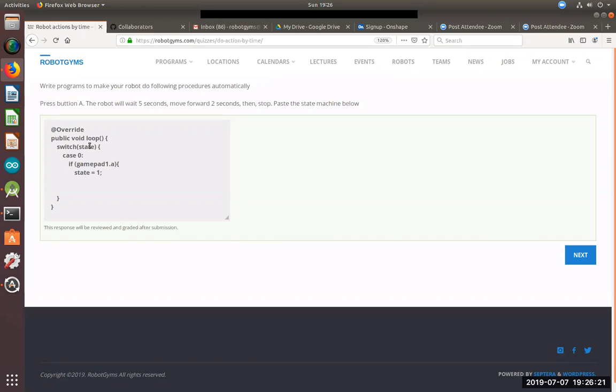And then you have a break. Always remember: if you don't say break, you will fall through. It doesn't check when you come back; you immediately go to case 1, whatever the next case is. You need a break. Most state machine bugs are just forgetting to put a break there. Why is this state gone? It only executes once. Why? Because it jumped to the next state without a break.